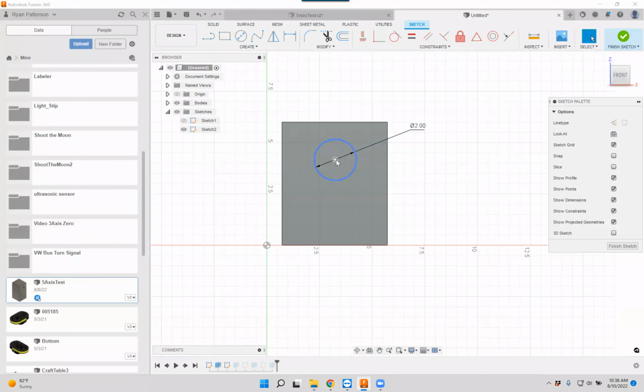If I want to have this circle always remain centered in this cube, regardless of the size of this cube, I'm going to draw a line, and then set the line type over here to be a construction. And we're able to snap that line to the edge of that cube, coming in, and it snaps to the center of the circle. Then again, snapping to the outside edge.